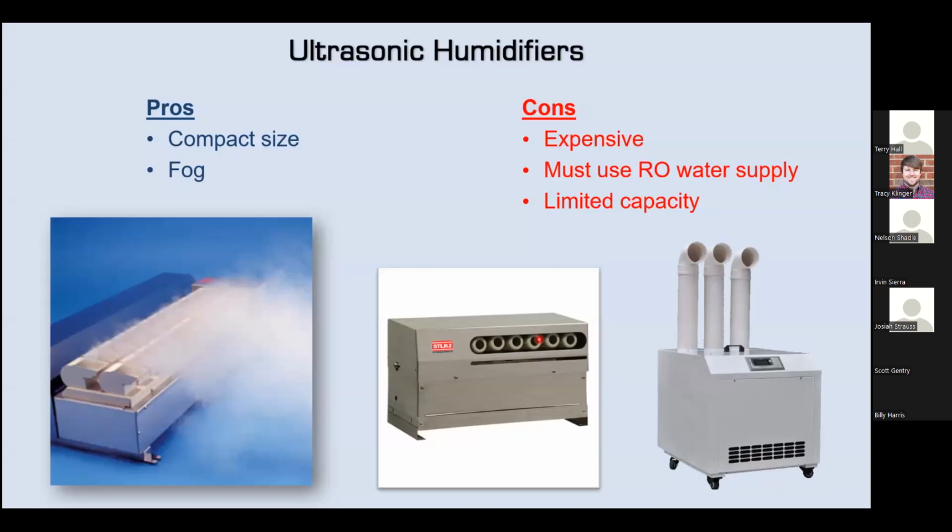You do see ultrasonic humidifiers occasionally. They're pretty well suited to some data center CRAC unit applications. The benefit here is that they spray directly into the space. The caveat to them is that they require RO water. They can be expensive, and there's a bit of a maintenance requirement on them. You don't really have an absorption distance associated with them in the space, and they're not blowing hot steam in the space, which can be desirable for some applications.